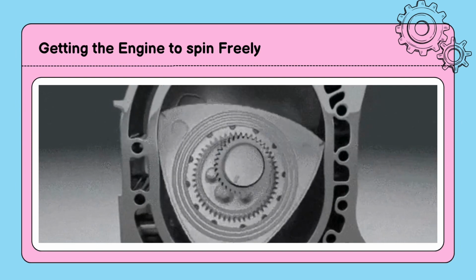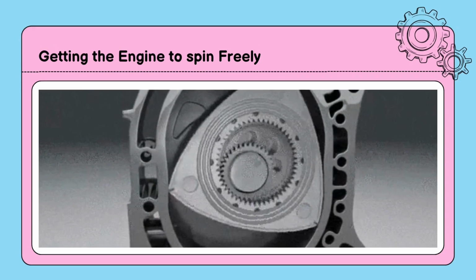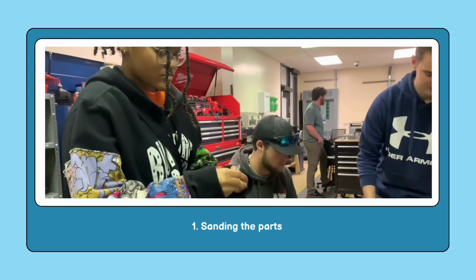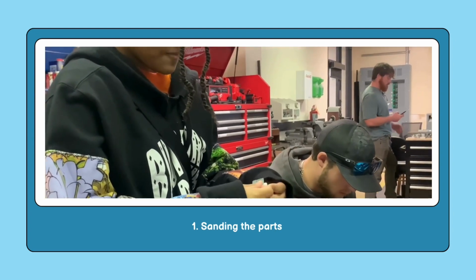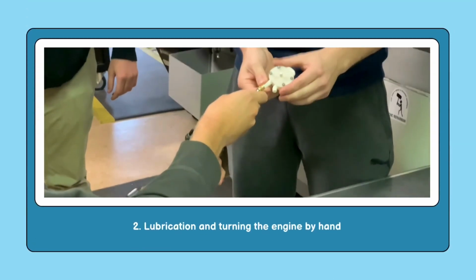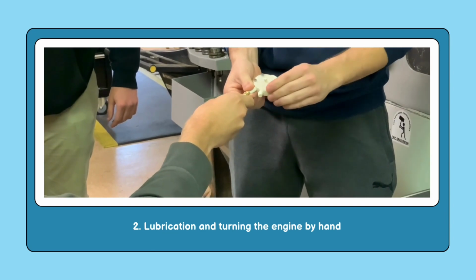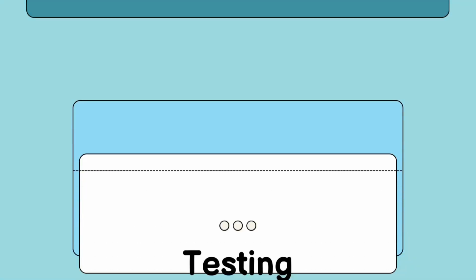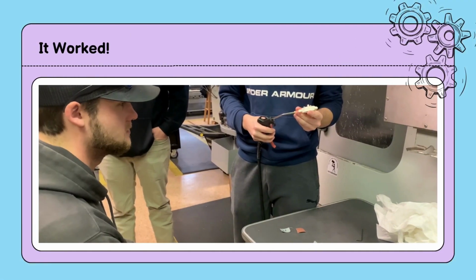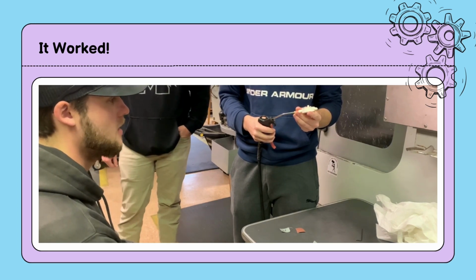Once it was put together, we struggled with getting the engine to spin freely. We overcame this challenge by sanding the parts down to have a smoother surface, as well as lubricating and turning the engine by hand and drill to get the engine to spin fluidly. After overcoming these challenges, the engine ran fluidly.